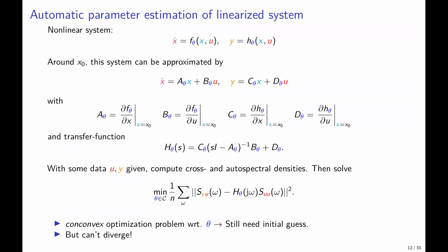So we want to find a good initial minimum, an initial parameter estimate. One way is you can, of course, say, okay, loudspeaker, I know the mass is maybe 10 grams and BL is around the order of 4. And that is already a good guess for this first problem to solve. And here is the idea that we have a nonlinear system, and then we linearize it. So we find what is the approximate dynamical system at, for example, the state x equals 0.